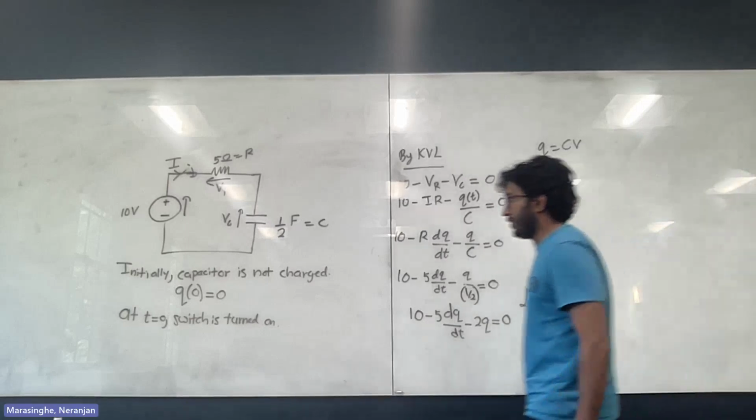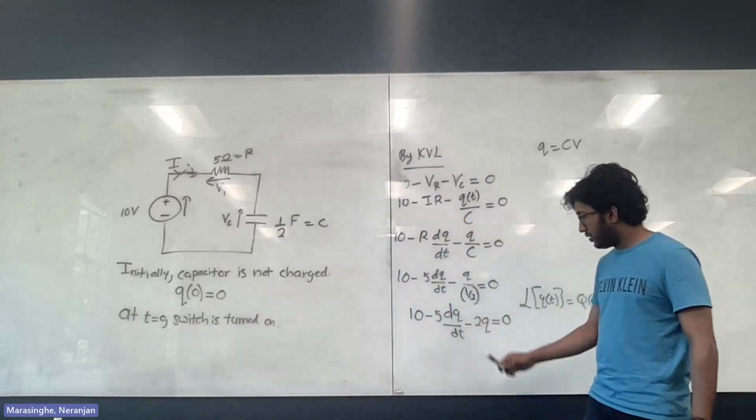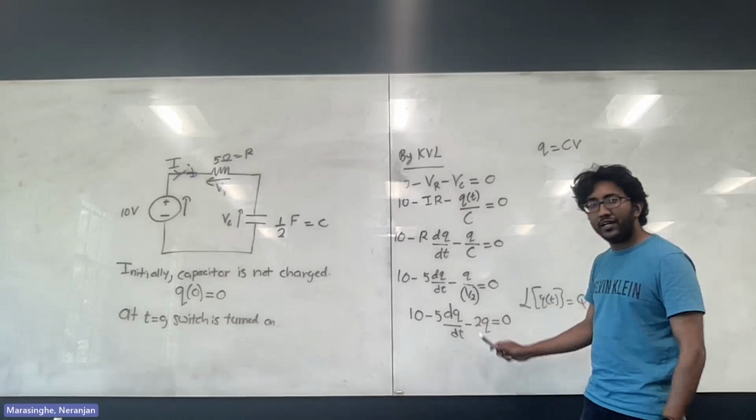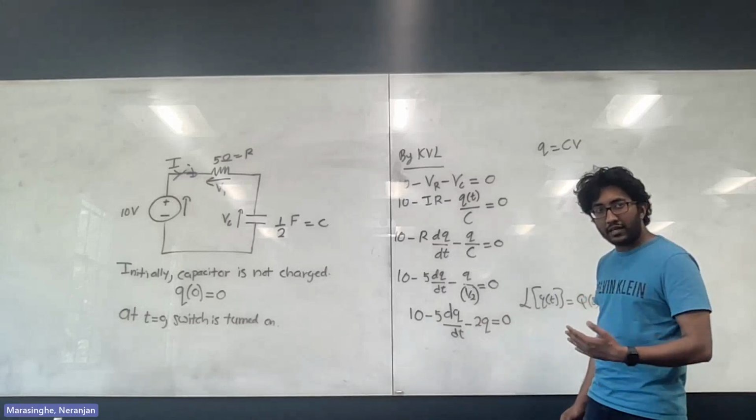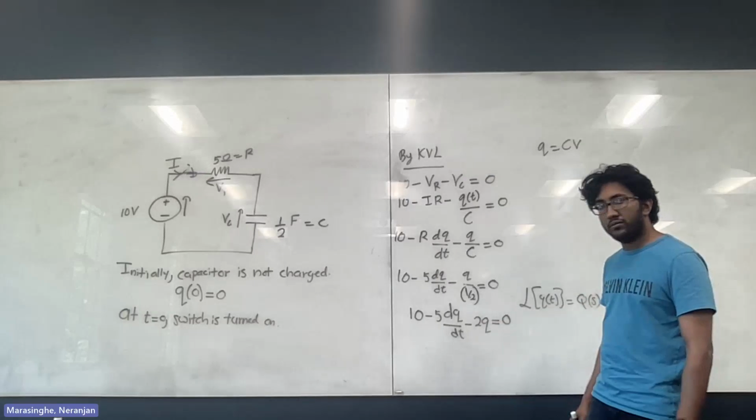Initial charge is 0, right? You would need this when you apply the Laplace transform. That's the Laplace transform of a derivative: s times Q(s) minus Q(0). Q(0) equals 0.